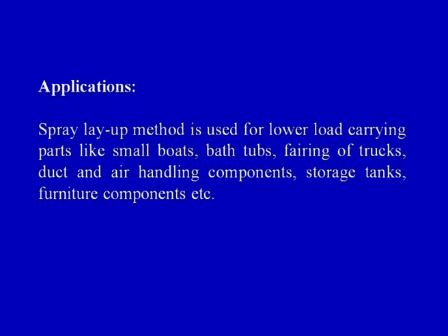Therefore they are used in small boats, bathtubs, fairings of trucks, duct and air handling components, storage tanks and furniture components. So the products made by the spray layup process are such that too much mechanical loading is not going to come. They are used for relatively medium mechanical loaded components where the loads are medium in nature, or there is no load at all. So spray layup has its own advantages and certain limitations, but still it is one of the common processes used for processing of polymeric matrix composites.